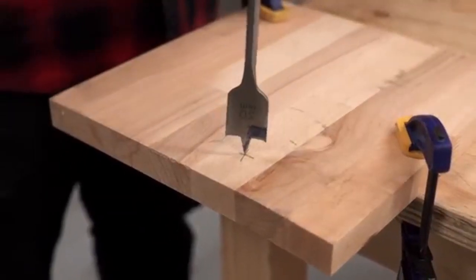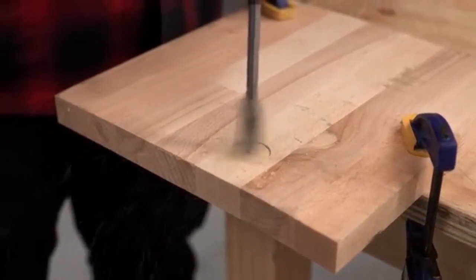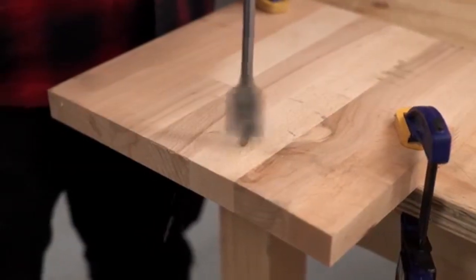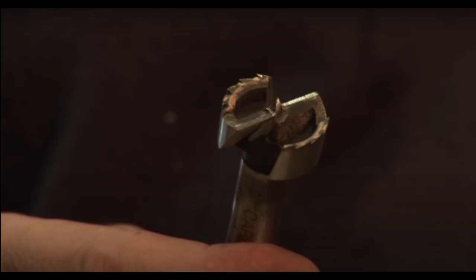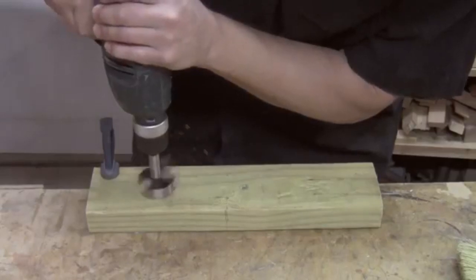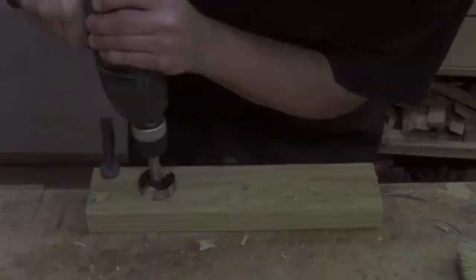Spade drill bit. It is a drill bit used to create much bigger holes and is relatively easier to use. To use a spade drill bit, it is important for the drill to be perpendicular to the workpiece. Forstner drill bit. It is used to form holes with a flat bottom. It is most commonly used in hardware installations, where a precise depth of mortise is required, such as kitchen cupboard hinges.